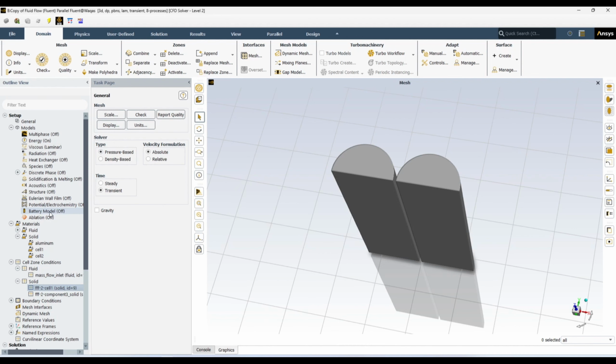Yeah, I understand R is normally not constant for the entire range of SOC, but for the sake of simulation, we can approximate, because from 20 to 80% SOC, R approximately remains constant. So you can use I square R for heat generation. But if you want to use a temperature dependent property, then you need to have some profile, or you have to use some UDF.